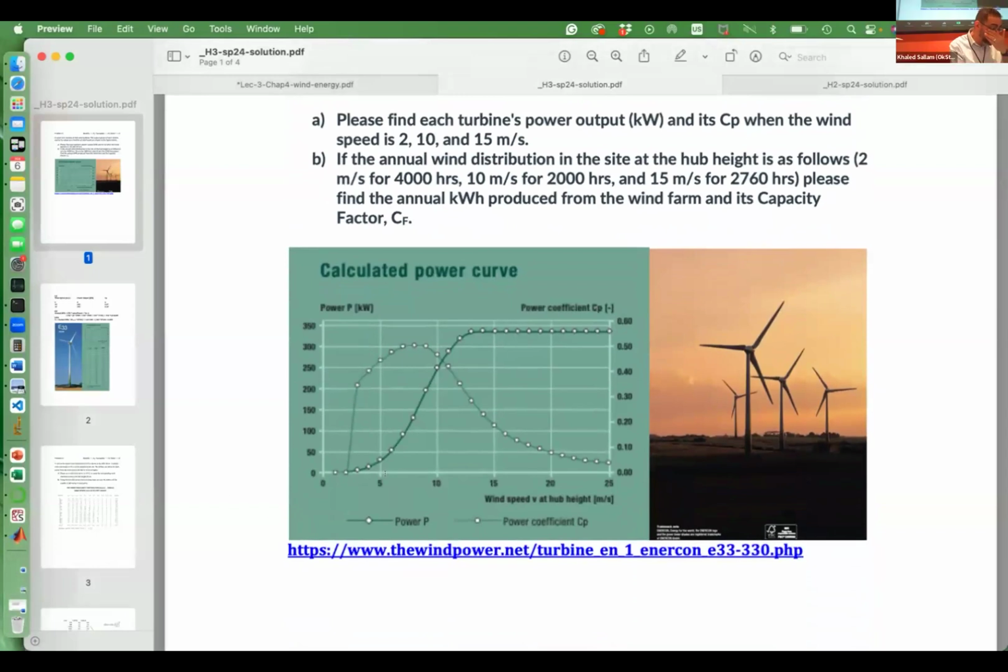So that's why you will end up with a curve like this. This is the output power. The output power is small, almost zero when you are less than the cut-in speed. There's a minimum speed. If you are less than this, you are not strong enough to even make it turn smoothly. And then we start extracting power, but the wind does not have that much power to start with. So even with my maximum CP, I'm not getting my rated power.